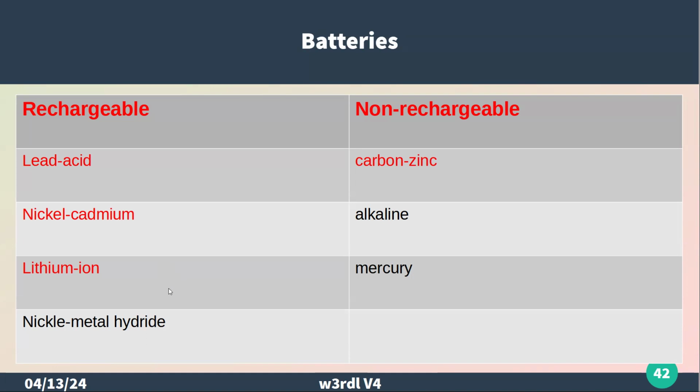And there are various lithium types now. You have lithium polymers, which you typically see used in radio control model aircraft because of the amount of energy per weight. They're very lightweight. Because it's in a plastic package and it has lithium in it, if it gets punctured, lithium and moisture don't go together, and it creates a fire, kind of like a thermite reaction.